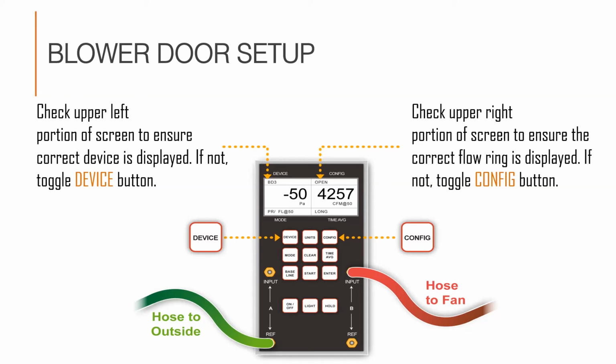The manometer needs to know the diameter of the opening on the face of the fan. Again, there are two plastic rings that you can use, the A ring and the smaller B ring, or the option to remove both and run the fan with the face wide open. It's critical that you configure the manometer to the appropriate opening size.